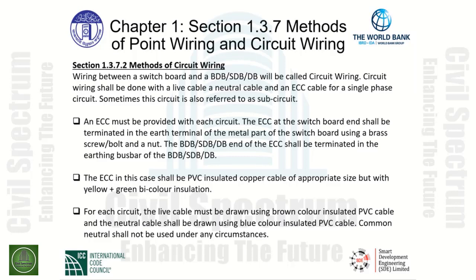The ECC in this case shall be the PVC insulated copper cable of appropriate size, but with yellow plus green bicolor insulation. For each circuit, the live cable must be drawn using brown color insulated PVC cable, and the neutral cable shall be drawn using blue color insulated PVC cable. A common neutral shall not be used under any circumstances.